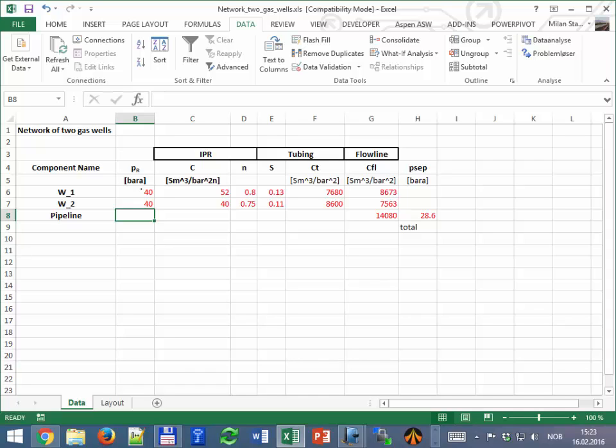Yeah, we have the PWF. Okay, we have the IPR. And if we say PWF, for example, is like 8 bar or something like that, then we get more or less kind of the maximum rate. Actually, the maximum rate we get if we put 0, if we put vacuum in front of the perforation. So let's do that just to get an estimate.